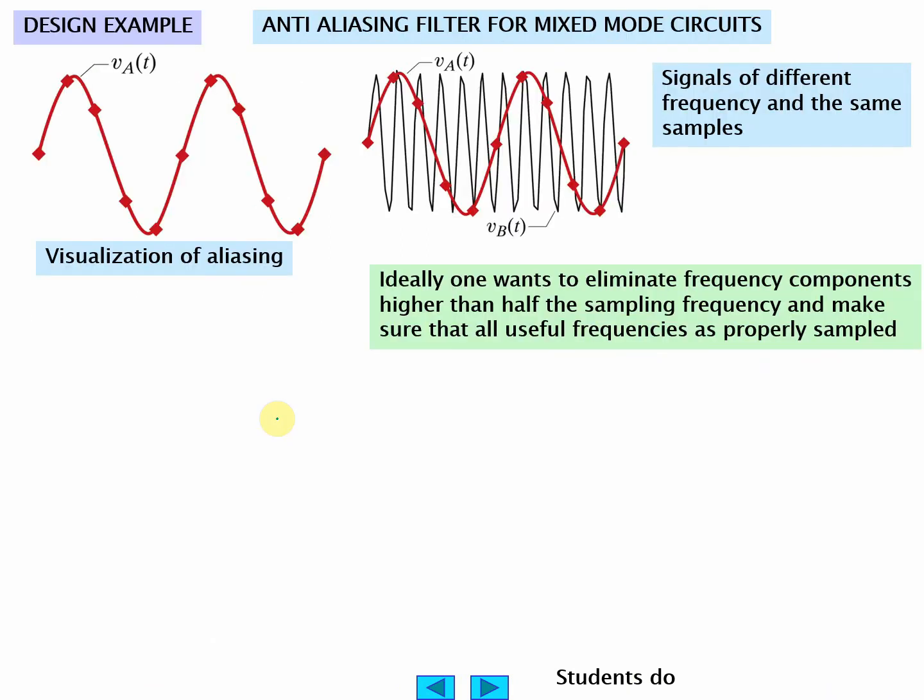Okay, here's an illustration of what aliasing is about. Here's a high frequency signal, and the big fat red one's a low frequency. But when you sample, you're sampling the points. You're getting the same point sampled. So when you reconstruct it, is it this red frequency, or is it 3 times higher frequency? You don't know.